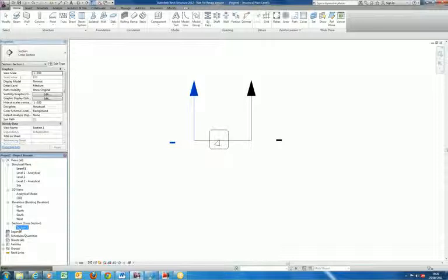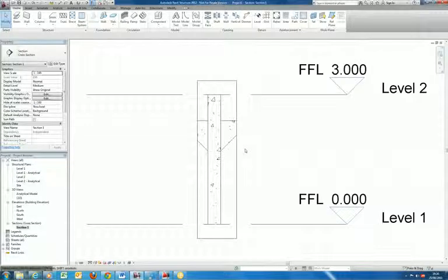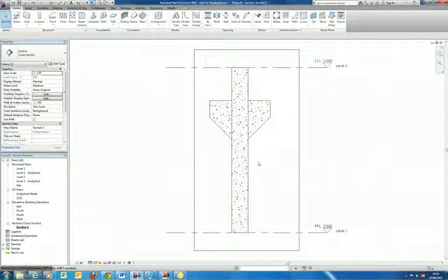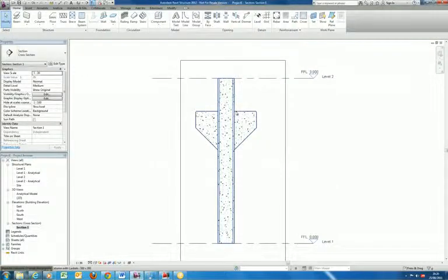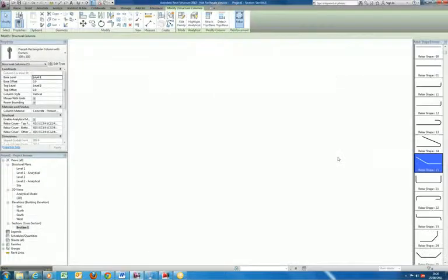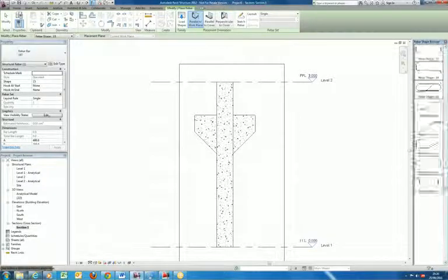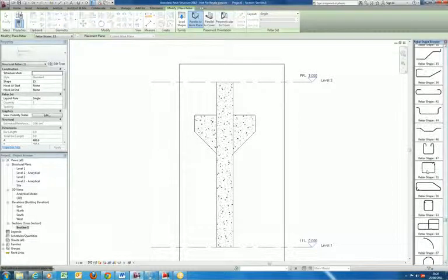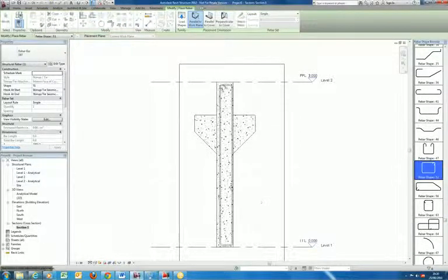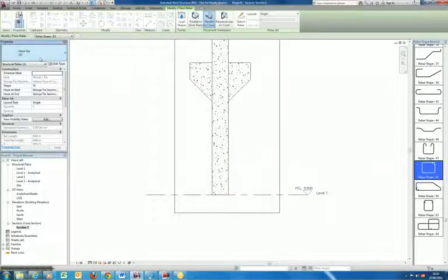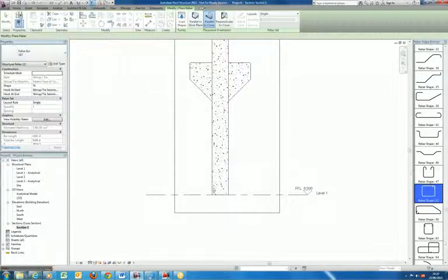I have a section through a standard column that's been loaded up from the library. I'm just going to change the crop view here that I want to detail. So I can pick the column member, and I can immediately go to Rebar and my shape code browser will appear. So in here I can pick my standard BS shape that I actually want, say shape code 51, and I can set this as parallel to cover, and let's specify these as 12R.